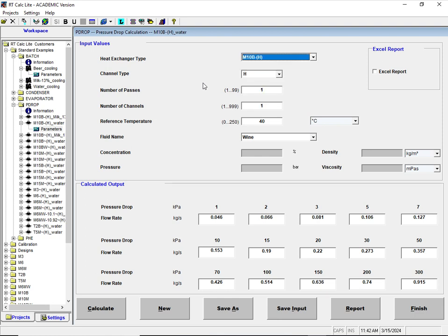Plate exchangers are very exotic things, and you're doing a lot with them. Typically you've got very low velocities in the plate channels because the pressure drops end up too high, and so we're running in what we would normally call almost a laminar range, and it's not quite really. Often they run in the transition zone or slightly turbulent. So there's a lot to learn about plate exchangers.